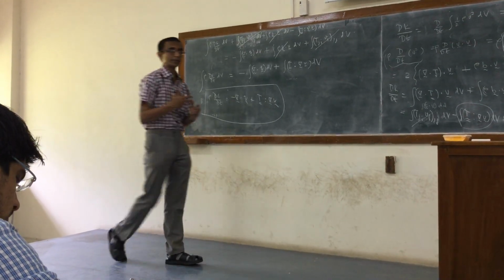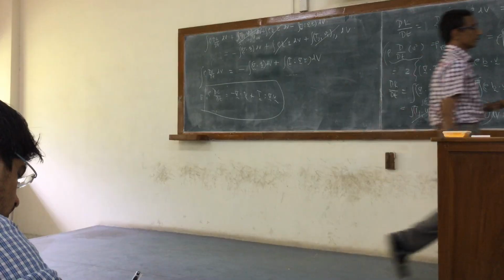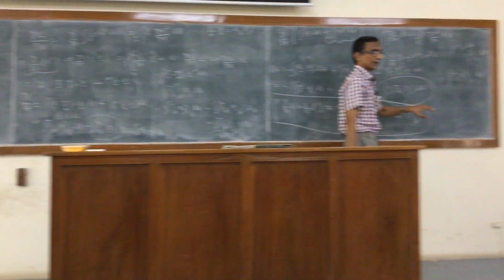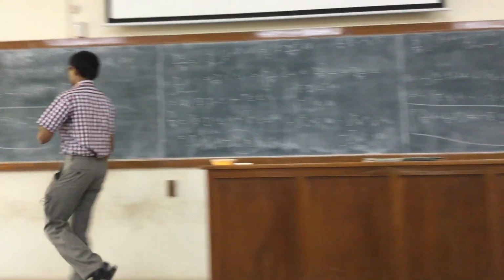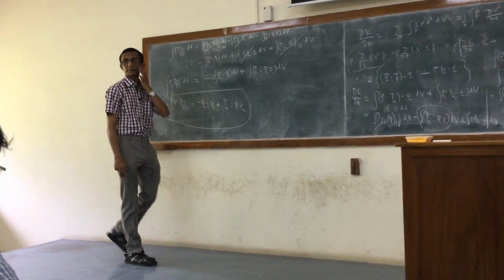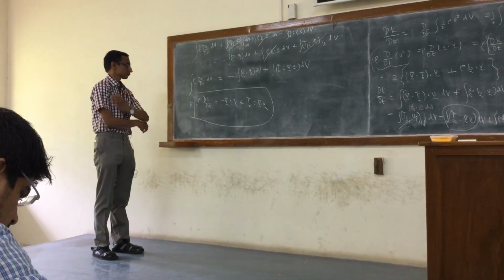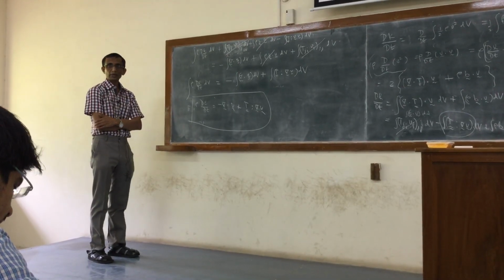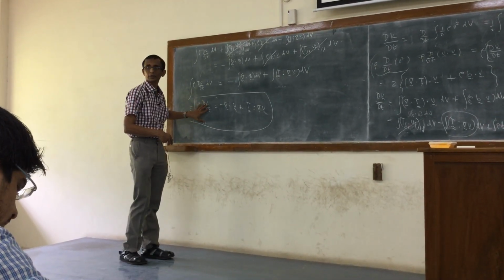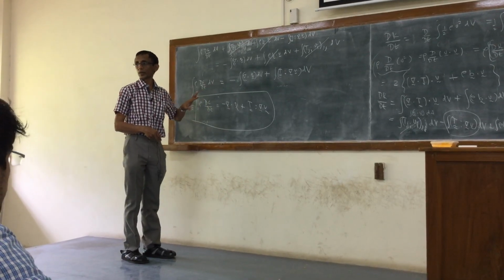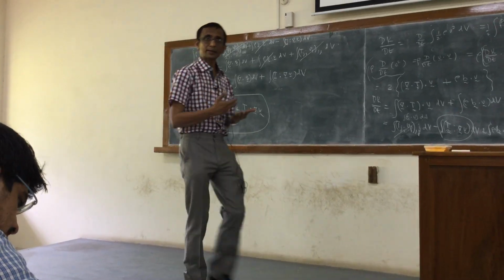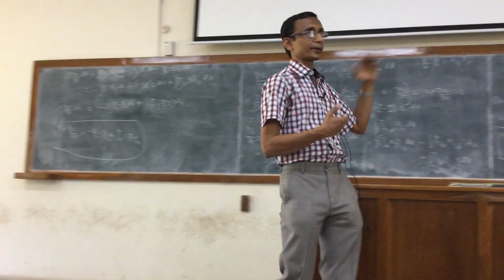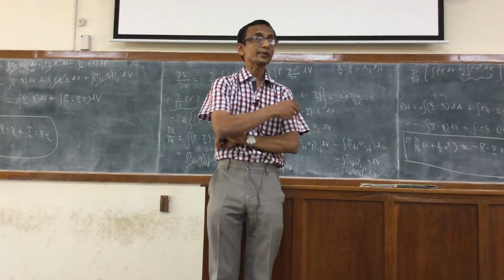So rather than dealing with these terms directly and the body force, I now have to deal with a heat conduction term and the viscous dissipation term. Effectively, you can see I have only the internal energy here, not the half V square. So it's been considerably simplified, but it's an exactly equivalent form. Are there any questions?